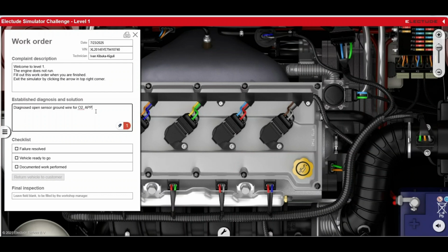So now, in this case, let's recap. I realized there had to be something common that was faulty on the oxygen sensor, accelerator pedal position, crank position, and MAP sensor. I misspoke earlier.